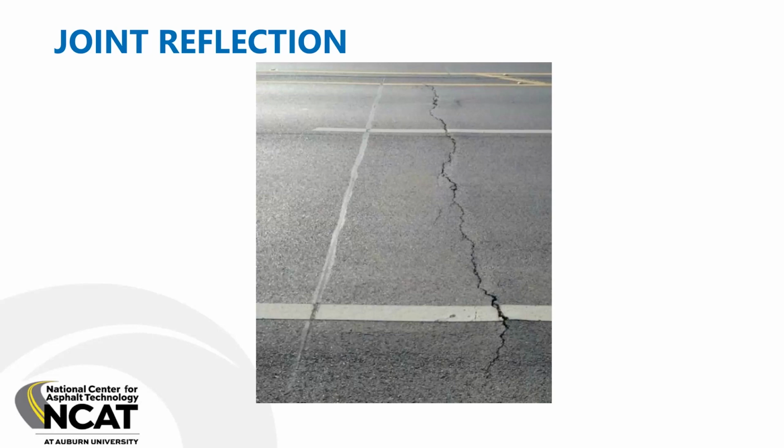But what they did was apparently, it looks to me like they used a roller wheel to record where the joints were instead of putting ground truth stakes or paint or anything like that to absolutely designate where they were. So when you went back and you used the roller and you identified the location where to do the saw cuts and the sealing, you were progressively off. So if you walk back to the beginning of the project, the cracking was exactly where the sawing and sealing was done. And the farther you got from the beginning of the project, the more off that was.